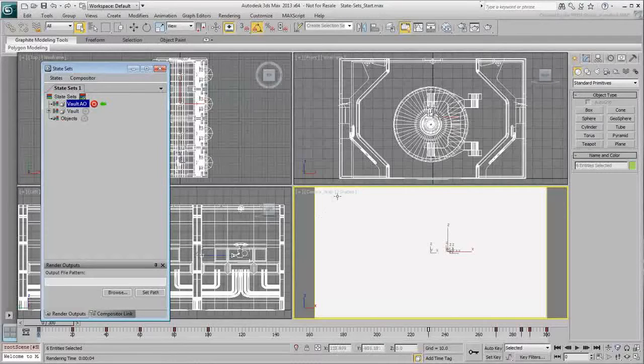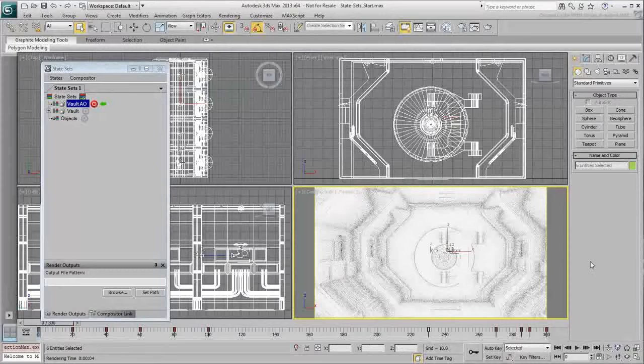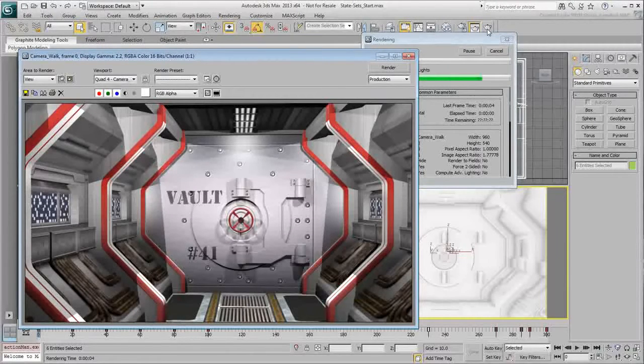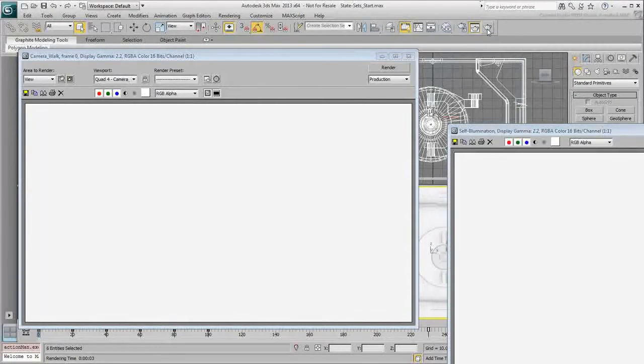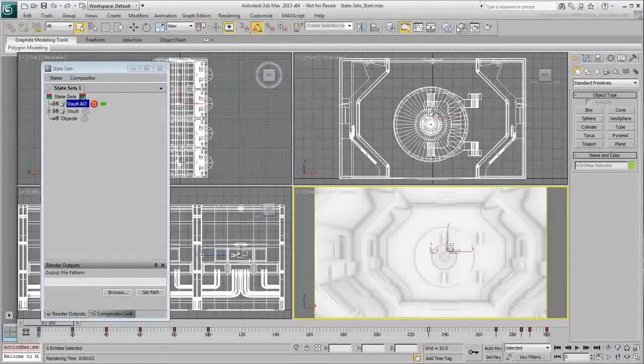Turn the viewport from shaded to a realistic mode. Now you begin to see something. Ambient occlusion works by adding contrast where surfaces come close together at a certain angle. By using this black and white information in post, you can enhance a rendering quite extensively. The trick, of course, is to render out such a map. At this time, the scanline renderer cannot help you. You need to use the Quicksilver renderer, a hardware renderer that enables you to render what you basically see in the viewport. Go to the Render dialog.